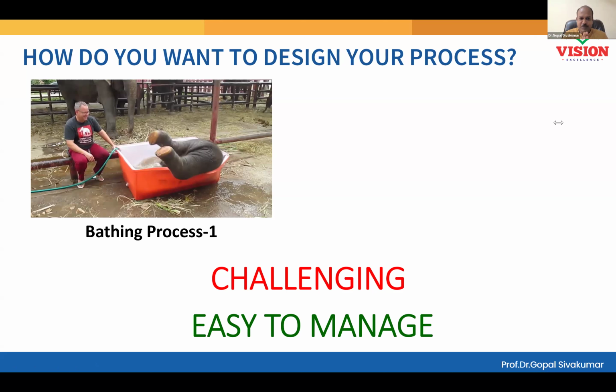Yes or no? Any process you are running can be defined by the spread of the process. What is the formula to calculate the spread of the process? Any process? Six Sigma. You developed that understanding throughout the course. If I simply calculate the standard deviation and then multiply by 6, that will help me to understand the spread of my process. And the customer has already given me a tolerance. If the spread of your process and the customer-provided tolerance are almost the same, like the elephant and the tub, then your process will also be challenging for you.